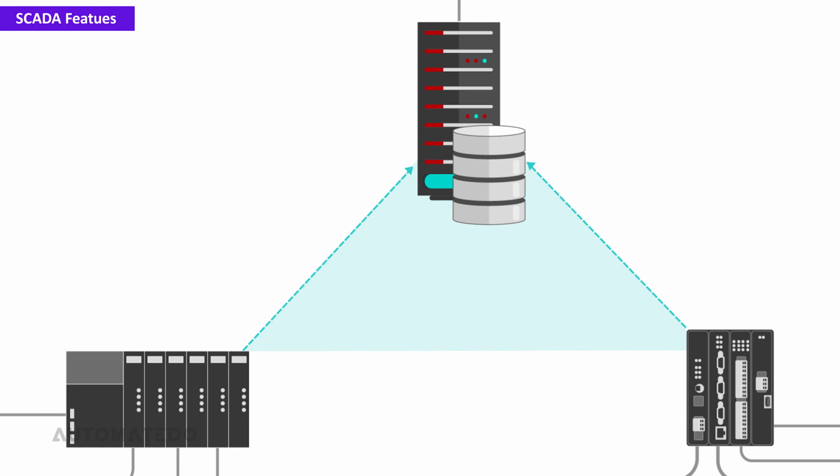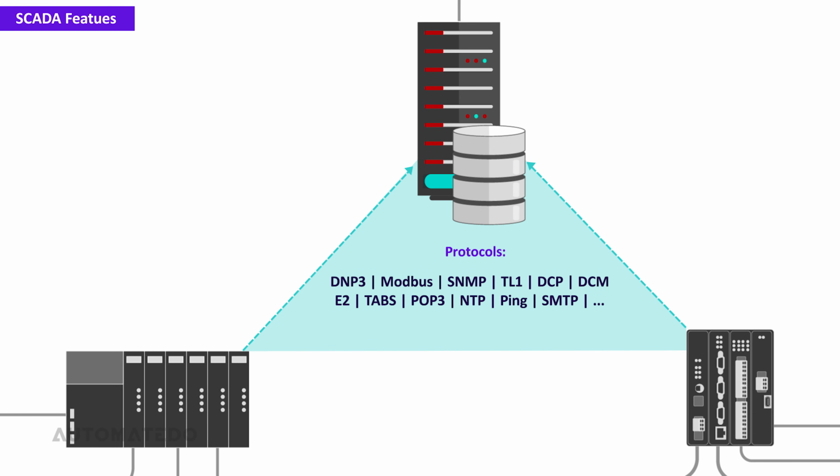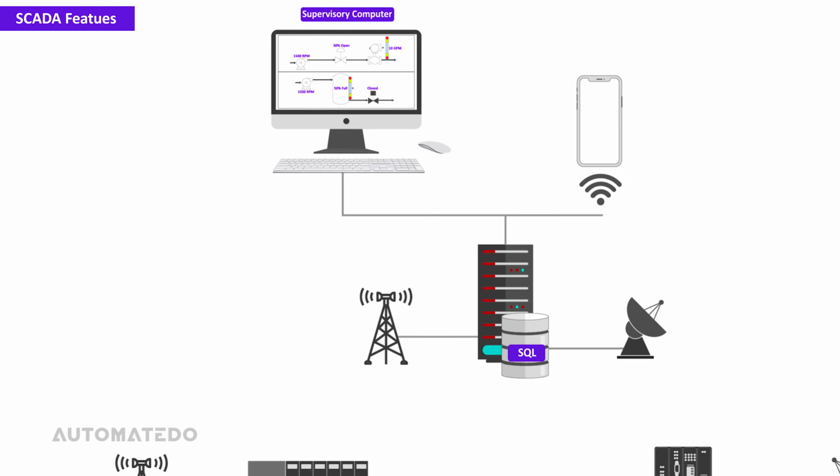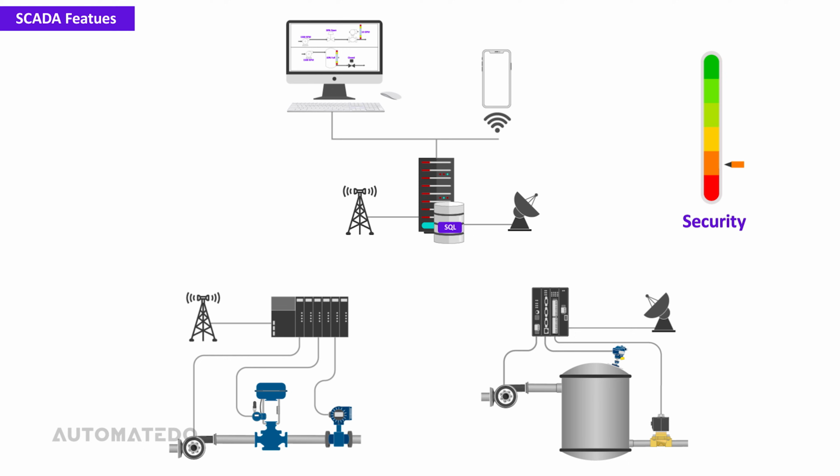The SCADA system's communications options are many and have evolved to keep up with new technologies. The embedded HMI software is not integrated with tag databases, so you must buy extra software to create or import your tags. If security is a priority, then the SCADA system is not a suggested solution because the SCADA system switches from proprietary technologies toward open alternatives.